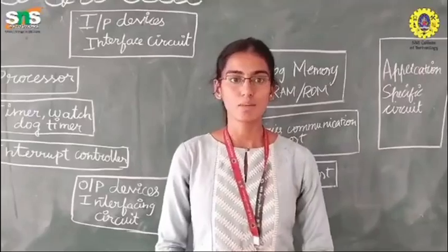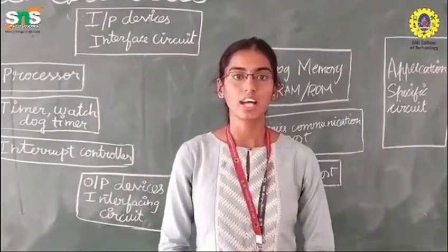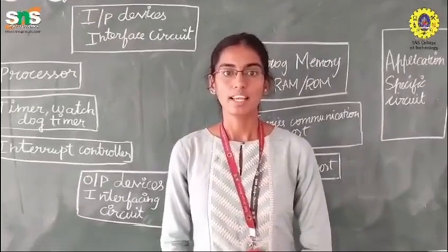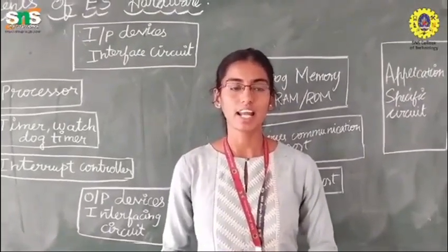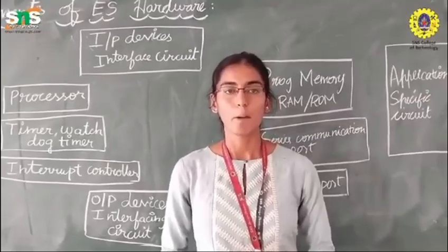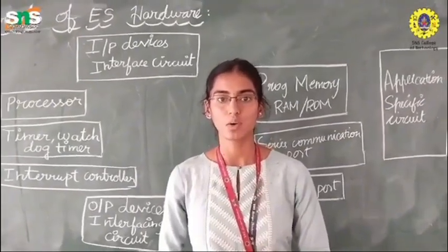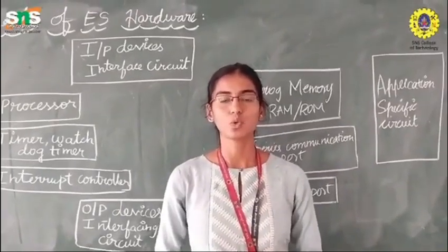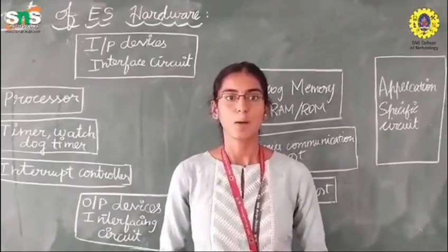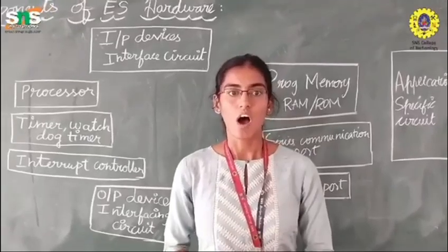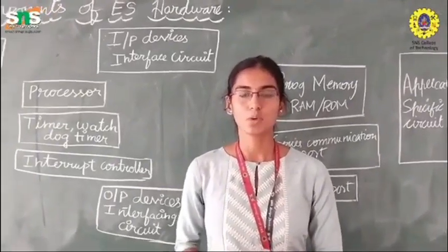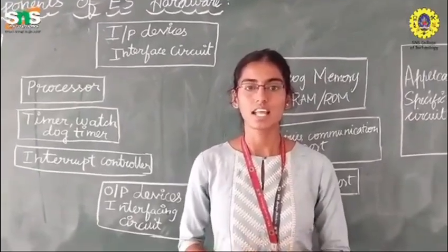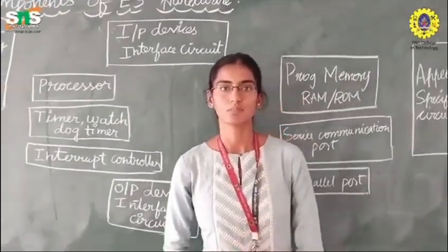Power supply. The power supply is a component in the electrical unit responsible for powering up the electrical load of the embedded system. While a 5V power supply is generally required, the range can go from 1.8 volt to 3.3 volt depending on the application. To ensure system operation, a smooth and efficient power supply is a must. The power supply unit can either be line or battery powered. Some embedded systems use an independent power supply while others leverage the same source as the larger technology being powered.